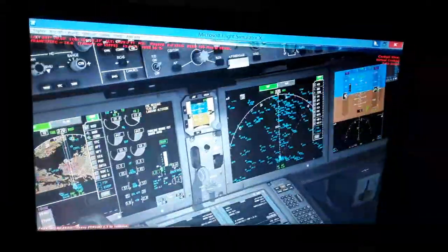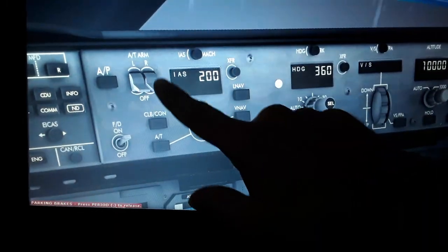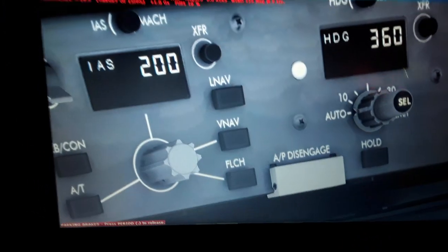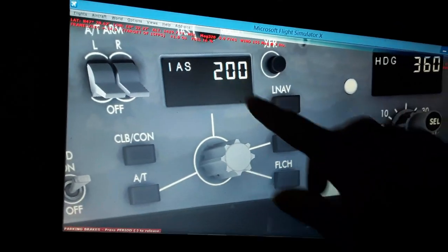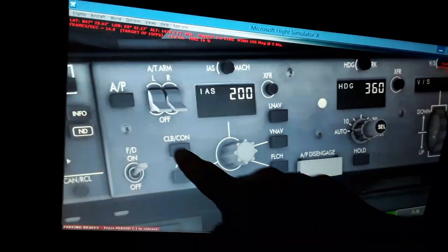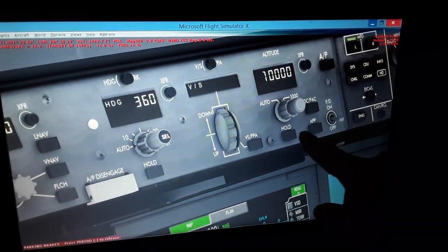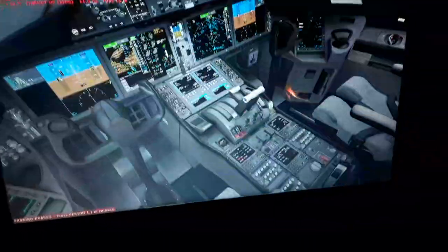So we have the autopilot flight director system panel. You can see autopilot engage, disengage, left and right, flight director, LNAV, VNAV, lateral navigation, vertical navigation, airspeed in nautical miles per hour, knots, flight level change, climb, continuous auto throttle, heading and bank angle hold, vertical speed, for localizer approach. So you will see all the functions in a few minutes after I show you a couple more things.